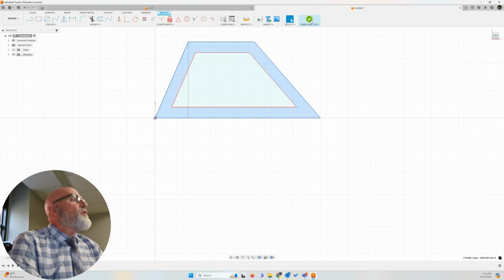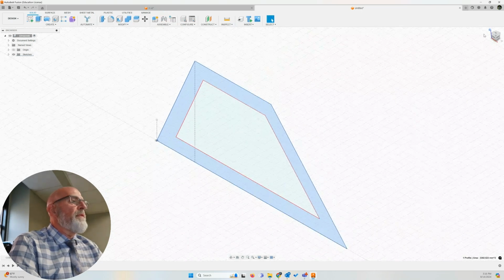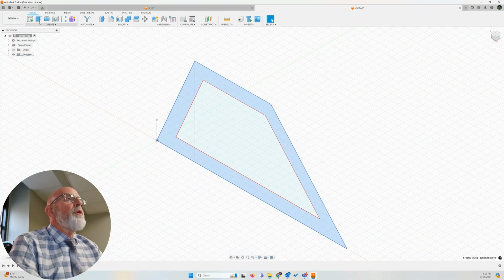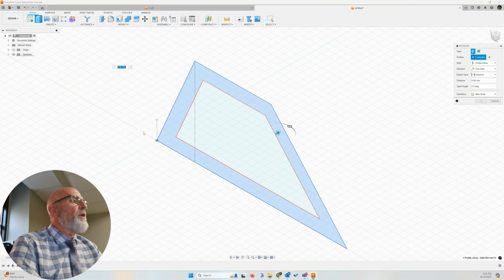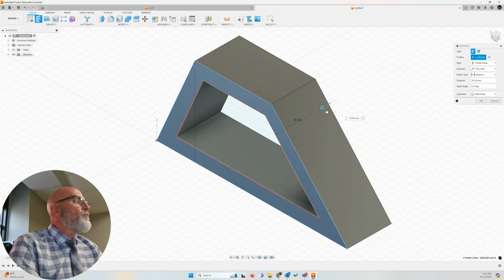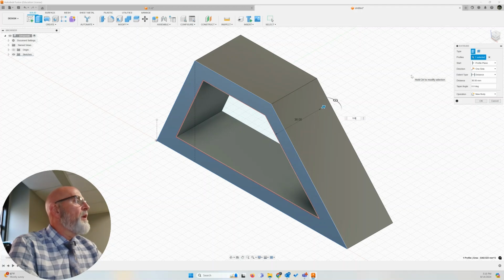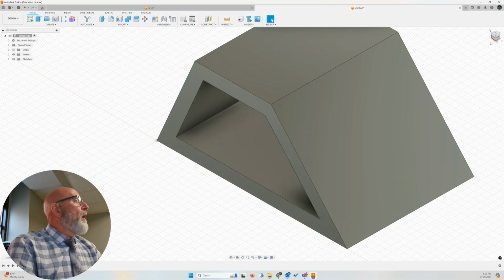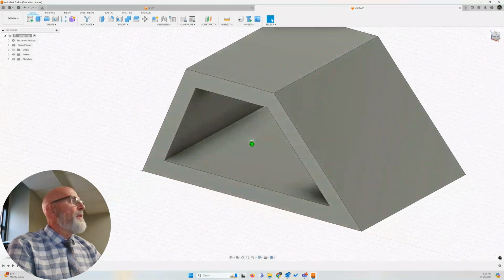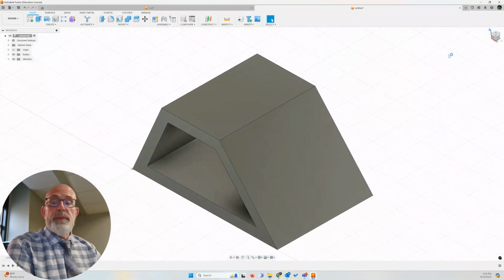Let's finish sketch. Home position. Let's extrude. Create, extrude, keyboard shortcut of E. There's a shortcut in the toolbar. We're going this direction and I want to go 100 millimeters. 20 on one side, 60 open in the middle, 20 open on the other side. Click OK. All right, so look at that. I've got my shape. We're not far from being done.